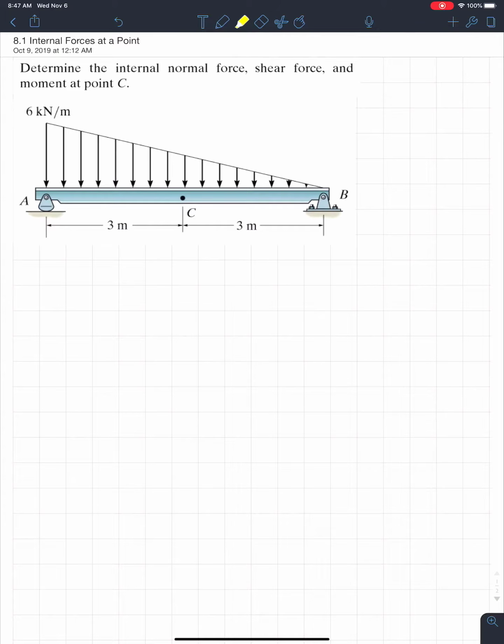convention. Now when we cut a beam, forces will appear. It makes sense. There's internal forces in the beam, and those internal forces are how the load will transfer in the beam to the supports. Now we're going to calculate those internal forces, but again, like I said, it's going to follow a very specific sign convention. I'm going to show you guys all of that.